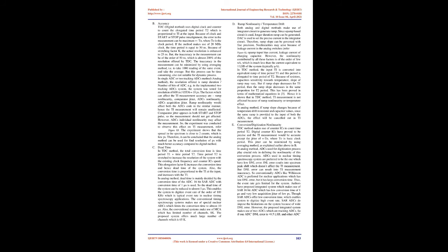In the analog method, dead time is mainly decided by the conversion time of the ADC. A 16-bit SAR ADC with conversion time of 1 µs is used. So the dead time of the system can be reduced to almost 1 µs. This enables the system to digitize event rates of the order of 100 kHz, which is a typical event rate in nuclear timing spectroscopy applications. The conventional timing spectroscopy systems make use of special nuclear ADCs which limit the conversion time to almost 10 µs. Also, the conventional systems make use of an MCA which has a limited number of channels, 8K. The proposed system offers a much larger number of channels, which is 65K.